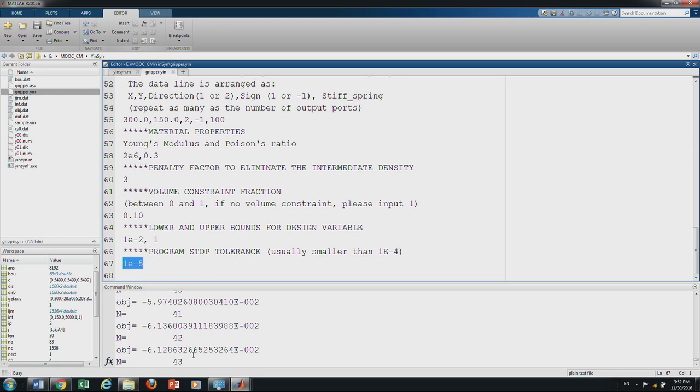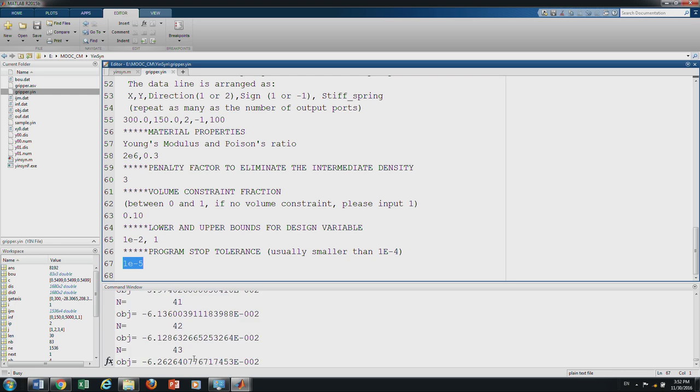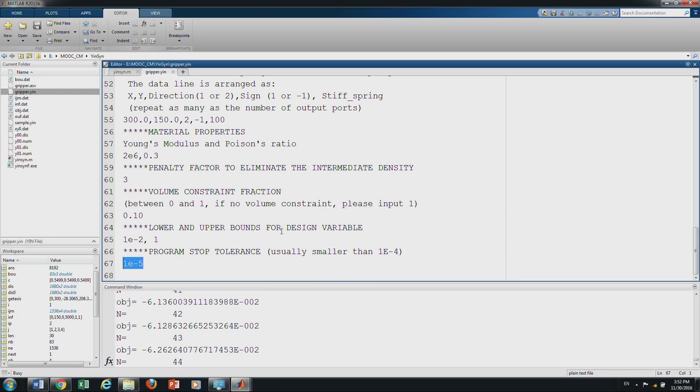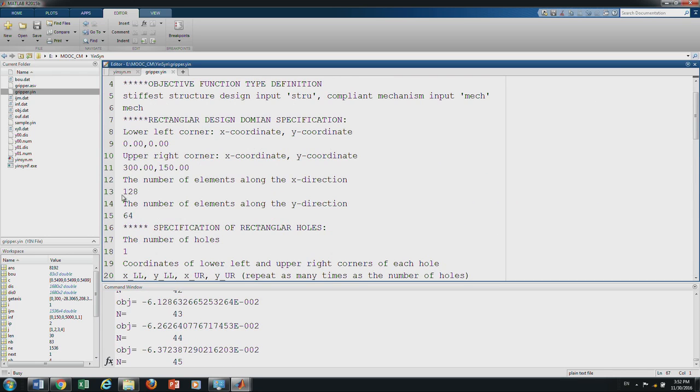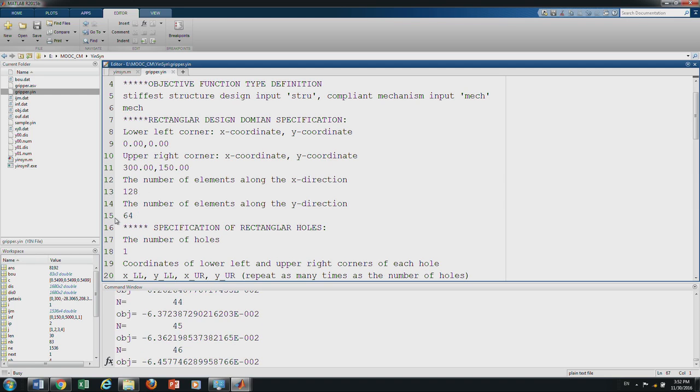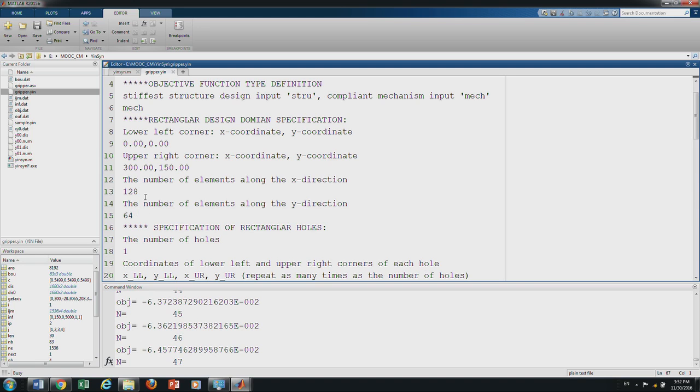Now, with all this talking we are still in the 43rd iteration, it is going to take a little bit more time. You can keep on doing it. Originally we had 64 and 32 elements, now I put 128 and 64. If you want you can make it 256 and 128, push the limit of your memory, or whatever is coded in this Fortran file, right.